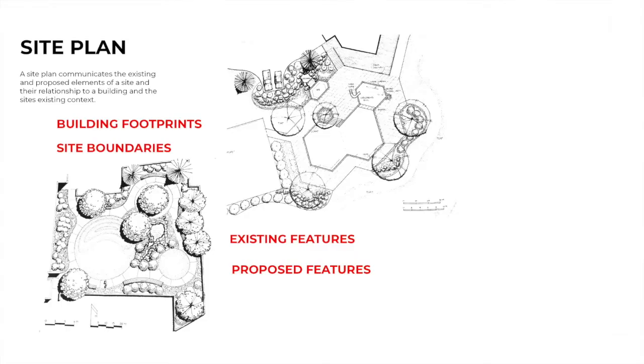In a site plan, it's as if we are a bird flying over the site, looking straight down at it. And so all of the measurements or dimensions are measurable to a scale or drawn to a scale. You can see a scale bar and a north arrow down here. And then we have a series of conventions in landscape graphics to represent one material from another.